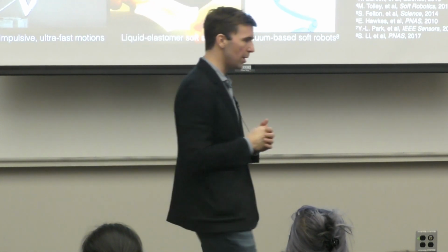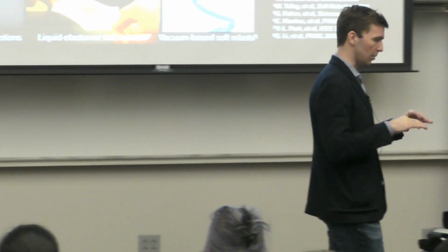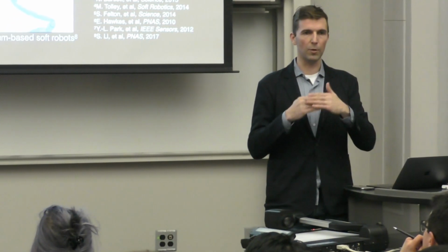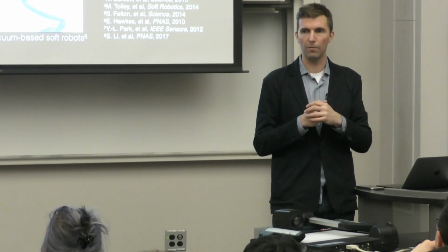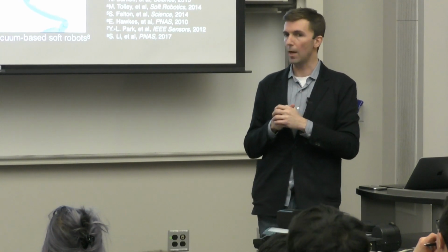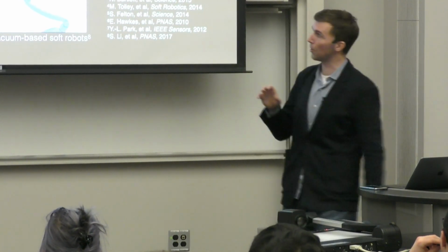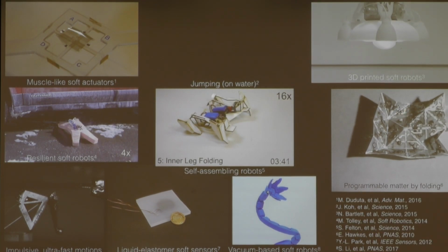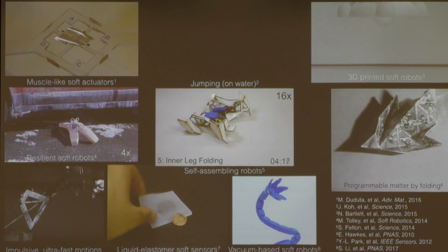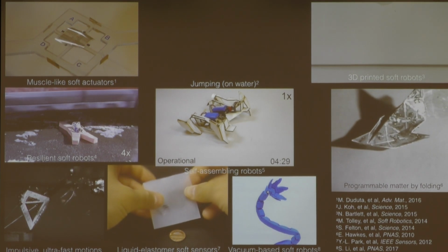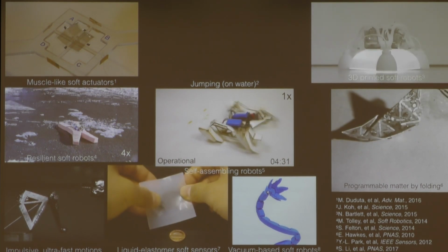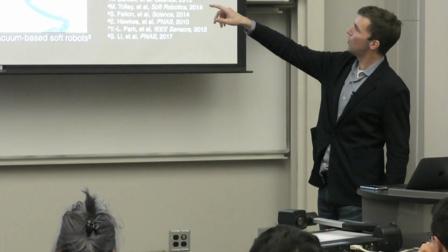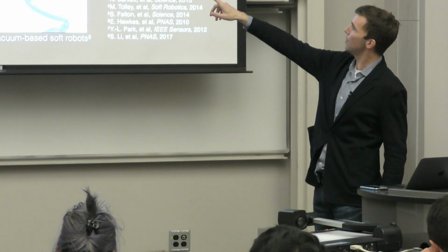And lastly, we use a combination of sparse carbon nanotube and silver nanowire electrodes, which don't interfere with interlayer adhesion and have negligible effect on the overall size and stiffness of the actuator. Sorry, that was long-winded. But we can make muscle-like actuators now with energy densities on the order of tens of joules per kilogram and human-like bandwidth. So we're very excited about that. And efficiency is hard to quantify. They're decent. We make soft robots that you can run over with cars. That's not super interesting anymore.